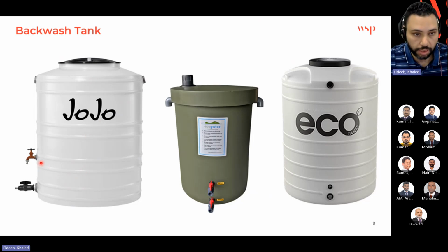It could be reused. Actually, the backwash water volume is too much. So this is actually a good, smart solution to reuse this water instead of wasting so much water every time we do backwash, and it could be recycled. But we need a special arrangement for this process, as I just said, and I'm going to cover it later in the overflow section, because we need to connect it back by gravity.